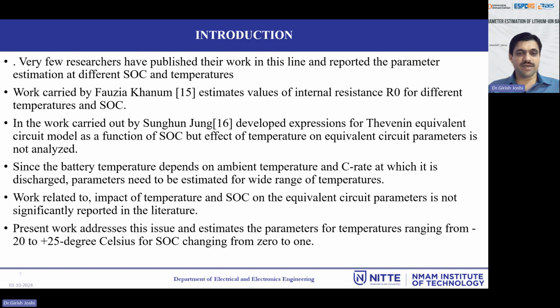Since the battery temperature depends on ambient temperature and the C rate at which it is discharged, parameters need to be estimated for a wide range of temperatures. Work related to the impact of temperature and SOC on the equivalent circuit parameters is not significantly reported in the literature.